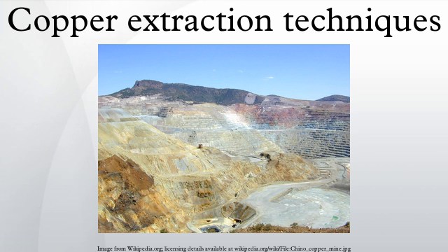In general, froth flotation is not used to concentrate copper oxide ores, as oxide minerals are not responsive to the froth flotation chemicals or process. Copper oxide ores have occasionally been treated via froth flotation via sulfidation of the oxide minerals with certain chemicals which react with the oxide mineral particles to produce a thin rime of sulfide, which can then be activated by the froth flotation plant.